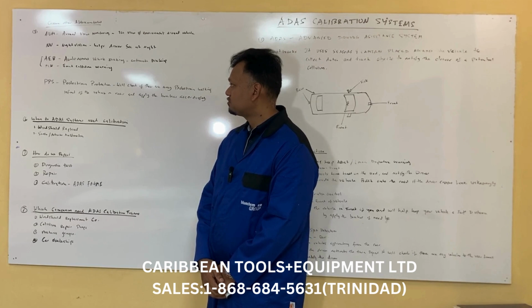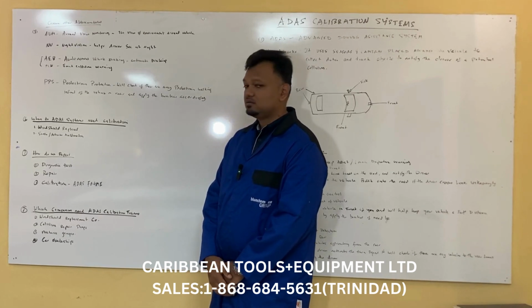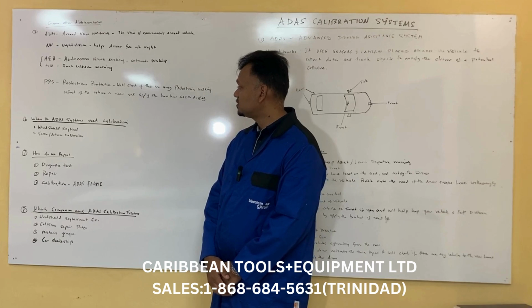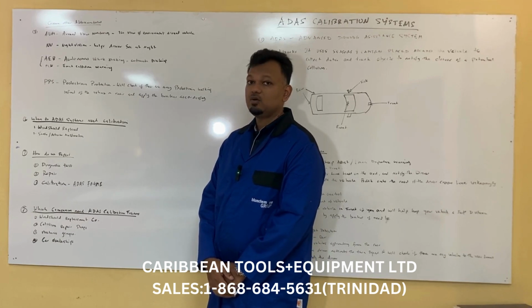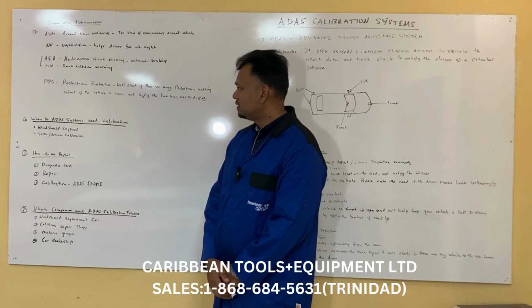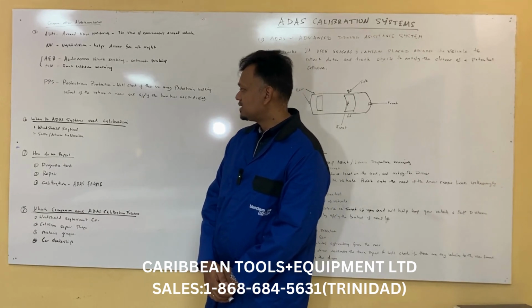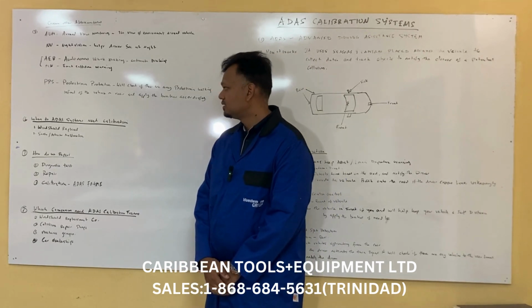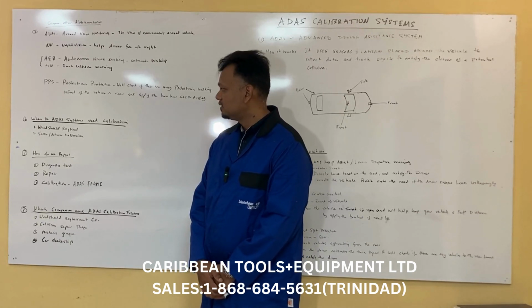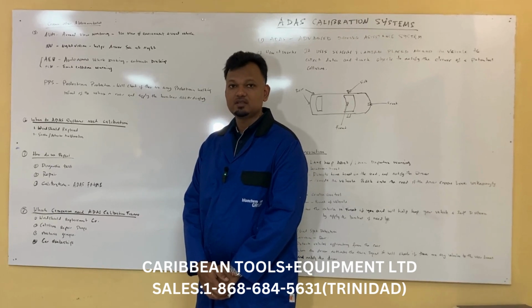PPS, pedestrian protection. All right, this will check if there are any pedestrians walking in front or to the rear of the vehicle and will automatically apply the brake accordingly. So when do ADAS systems need calibration? When there's a windshield replacement or sensor actuator failure.